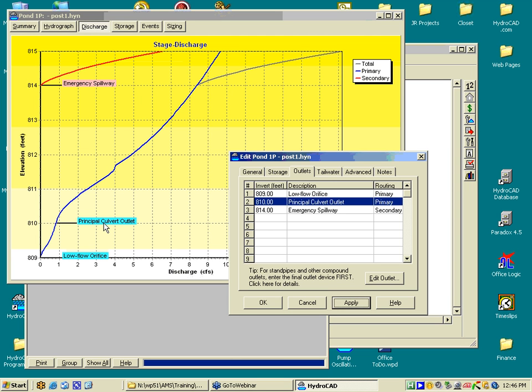We've got a new rating curve and a new routing operation. This little kink, by the way, is occurring when the pipe fills completely, when the hydraulic radius increases more rapidly than the wetted area. And so there's a slight decrease in discharge.